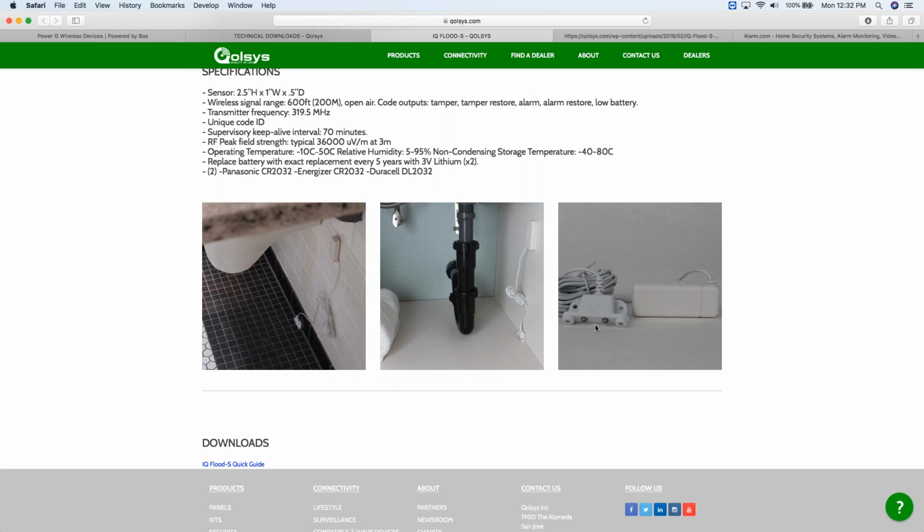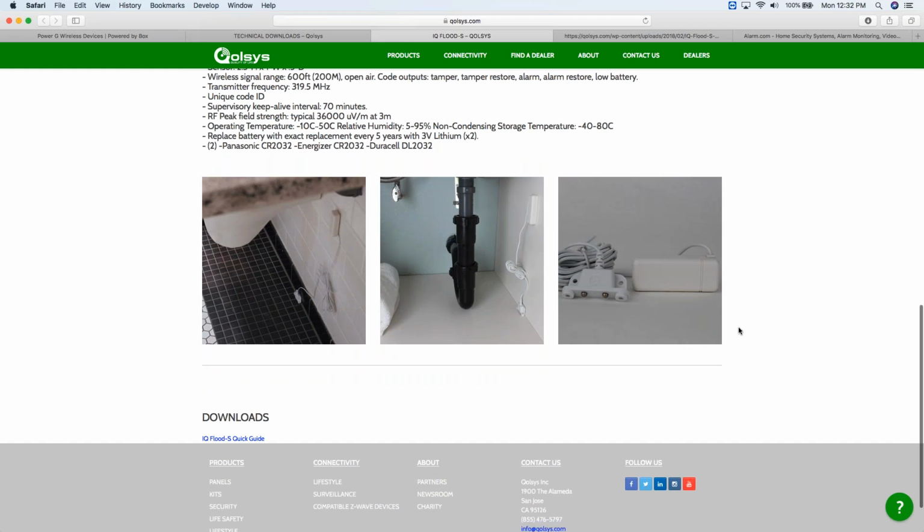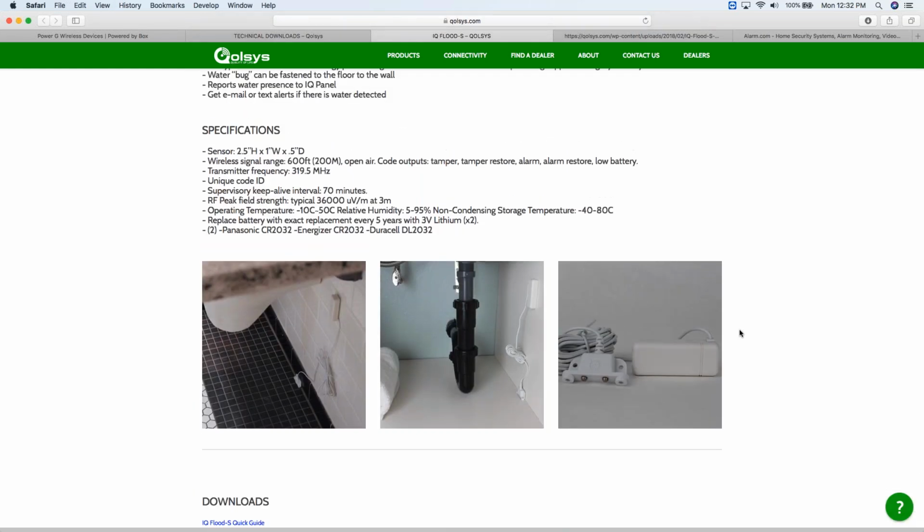It's got to be shorted for 12 seconds before that sensor will trip. So if you're using your screwdriver, connect those two contacts for 12 seconds and that signal will go. Or put it in a bowl of water for 12 seconds and get that sensor to go, right? But there is that threshold of 12 seconds before that sensor will trip, okay?